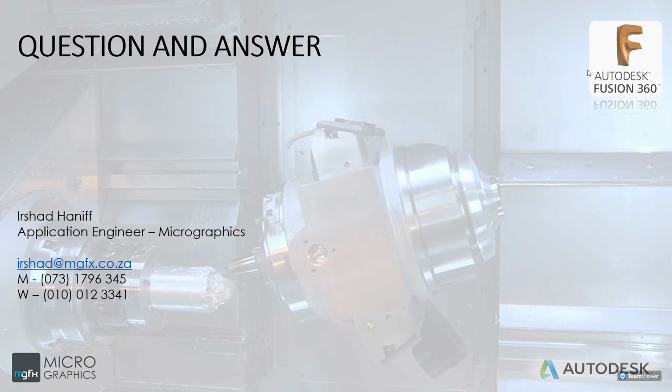Yeah. Can you bring in standard components, like say a motor that you've got from Beckhoff or something? Can you put that in Fusion 360? Yes, you can. Like I said, with any CAD, you can bring in any type of data from any other software. If you're getting that motor, for example, from their website and their catalog, they'll probably give it to you in step file, which is a general CAD format. And you'll be able to import that step file directly in and build your design around that.